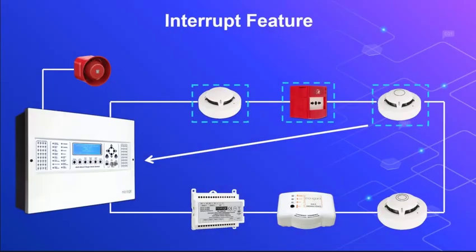In order for the alarm signal from the detector, button, and field control units to reach the control panel with priority, an interrupt signal is generated. Transmission is made to the exchange as soon as possible without waiting for the query time to end.